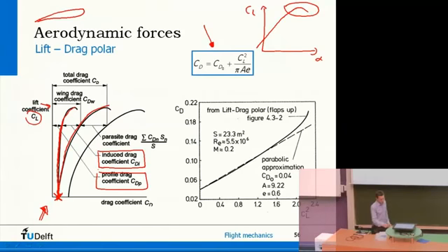So if you look at the whole aircraft, then the actual drag-lift relationship looks the same, but the whole curve has shifted to the right, simply due to the fact that there are all kinds of elements which also create drag, like a landing gear, antennas, fuselage, and so on. So this formula here is basically a representation of that curve.